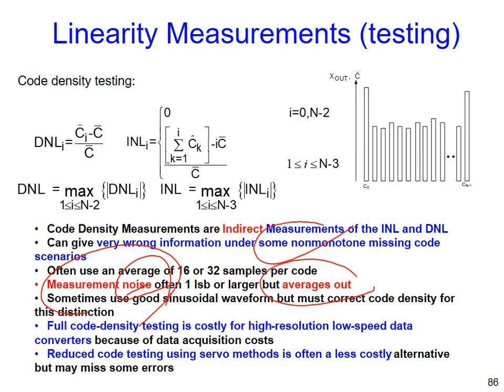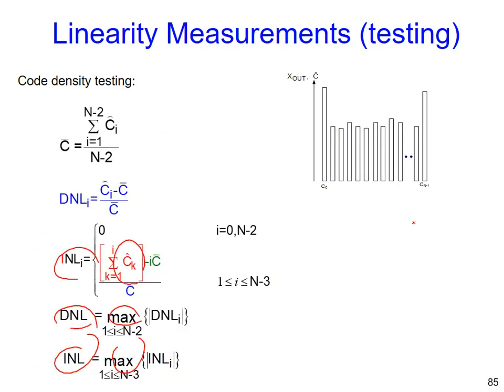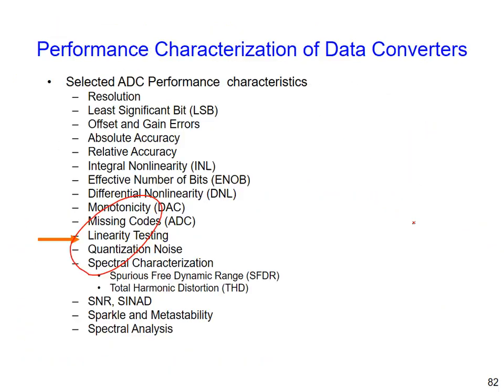No, according to noise, especially for high resolution ADC, it is impossible because the noise amplitude is much larger than 1 LSB. So right now you have 5, next time you have 9, next time you have 1, next time you have 12. Oh, it's really complicated. I promise you, you don't have any chance to check this one.